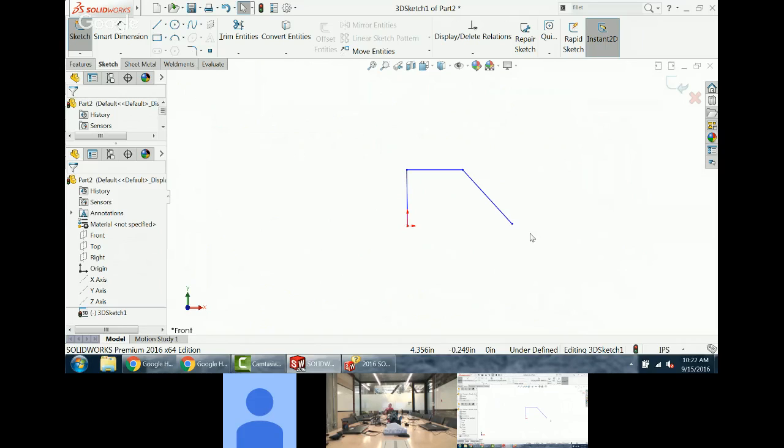So if you went in a perfect isometric view, so to speak, it would be moving equally in all three, X, Y, Z at the same time. No. When you're in an isometric view, it's a free for all. It's moving in all three at once. If you're looking straight down like that, it only works when you're using straight views. Okay. So if I'm looking at the front view, because I'm looking straight down the Z-axis, it's not going to move in the Z-axis.